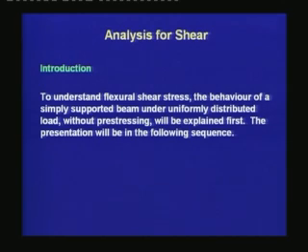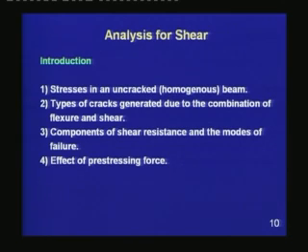To understand flexural shear stress, the behavior of a simply supported beam under uniformly distributed load without prestressing will be explained first. The presentation will be in the following sequence. First, we shall study the stresses in an uncracked beam. An uncracked beam is considered as a homogeneous beam where the effect of steel is negligible.